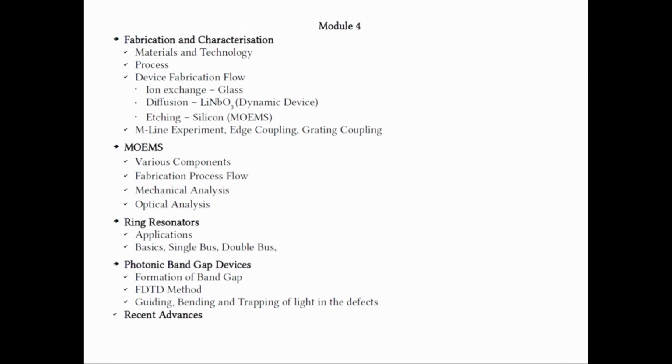Finally, we mentioned several other important emerging trends which we have not considered in this course, in particular photonic integrated circuits on active materials like gallium arsenide, indium phosphide, and so on and so forth. This is important in the future because these are the materials commonly used for optical engineering applications, and more importantly you can make lasers and other active devices on these active substrates. That is the importance of using compound semiconductor devices.